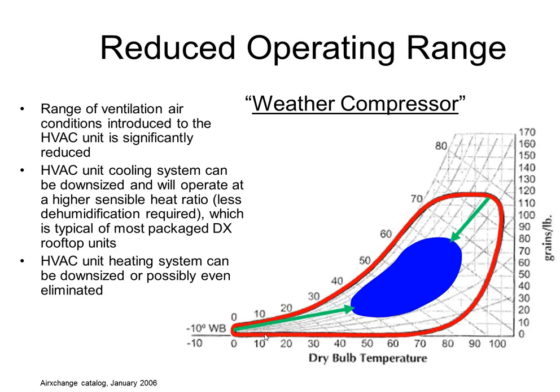Last slide chart for the whole class, I promise. The blue blob, if you will, is showing you the range of what a normal rooftop unit has to handle on an everyday project. I got to handle all the way down to 0 degrees or whatever. I got to handle up to 95 degrees or whatever it is there. Some really dry day, some really moist day. I got to handle everything in that red blob.